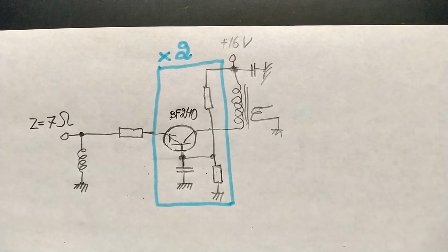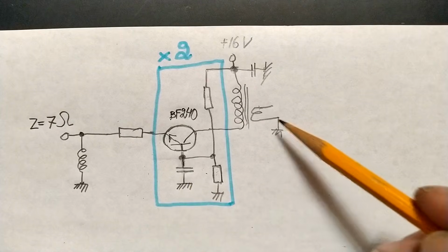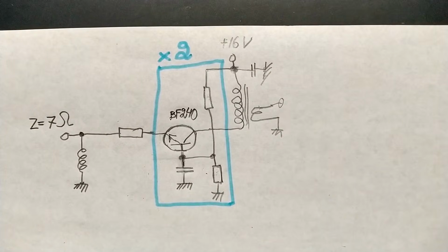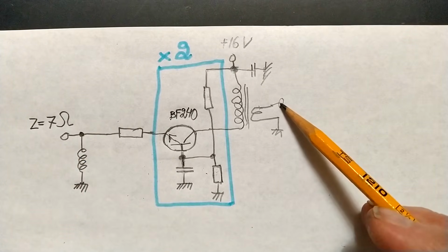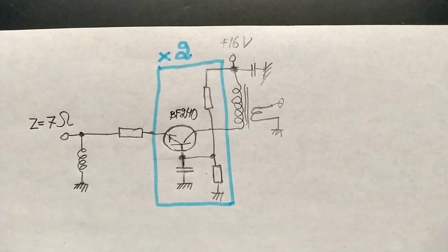Now, that is not enough at all. This thing gives far too much noise. And what comes after is unimportant at this point. The input impedance with the load that is applied normally is 7 ohms. And that's fairly nice for a 22 ohms output impedance of the crystal. It means the crystal is not much loaded.